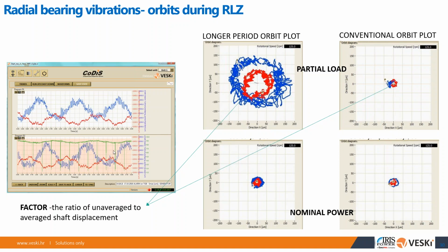We go to a slow roll. You can slowly turn the machine, but in between one trigger and another, which is one rotation, you get that low frequency 1x. So the shaft alignment doesn't have to do anything with the low frequency wobbling. This is happening on subharmonics. These are not related to machine frequency. If you see here, you have multiple turns, and let's say one in 5 turns, you get the precession.